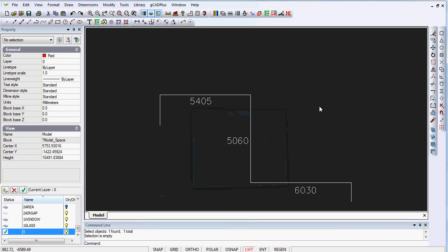Well, let's develop an accurate base plan for a rear area outside a very small house. This is the footprint of the house. So I'm going to start by drawing the footprint of the house. Let's imagine I've been to the site and on a little mud map I've measured the walls around. We're looking at the backyard through this area here.